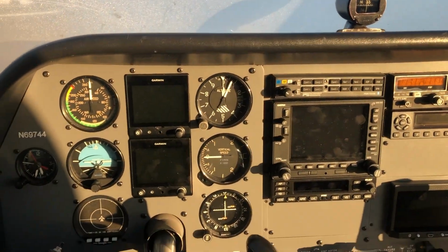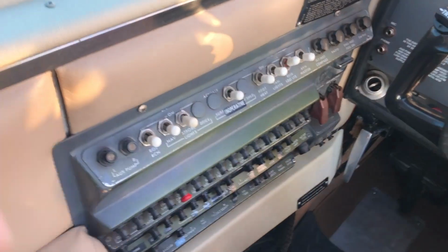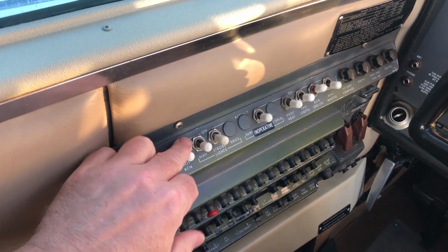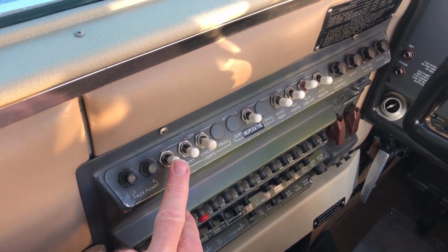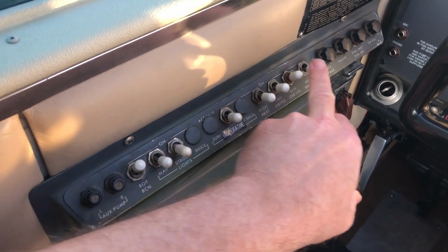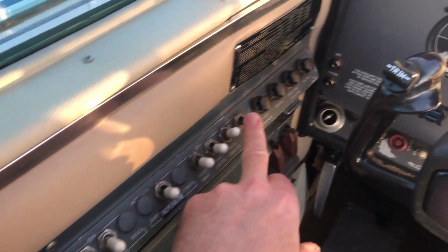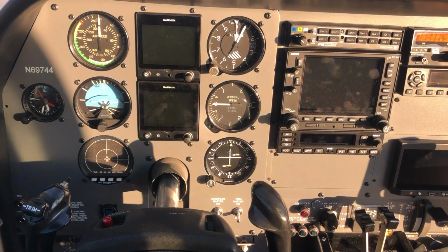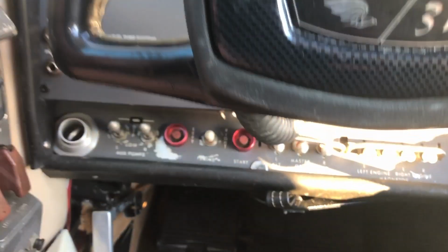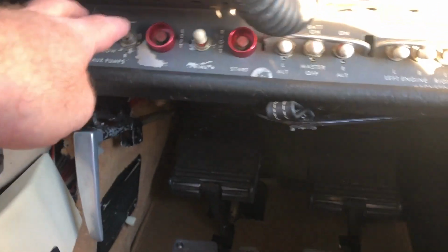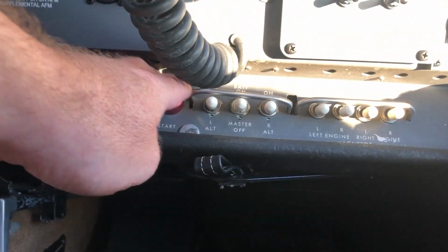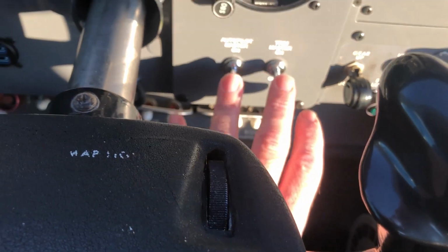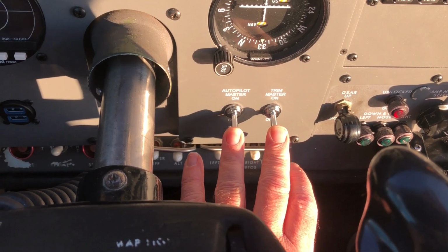So here's my pre-flight flow. Go down and check all circuit breakers are in. Check my electrical panel, everything should be off except I put the beacon on for start. Avionics master's off. There's really nothing to do up on the upper panel till everything comes alive after start. So now I continue down along the bottom panel. Check the fuel pumps are off. And then check everything's off, all the switches are off down here. And then check that my autopilot and auto trim master are off.